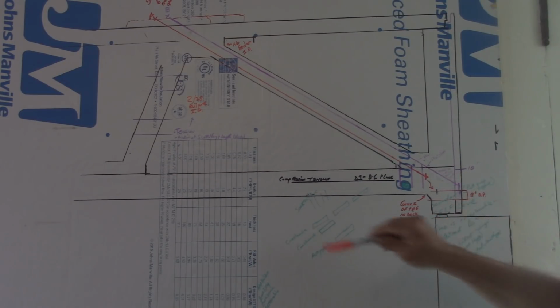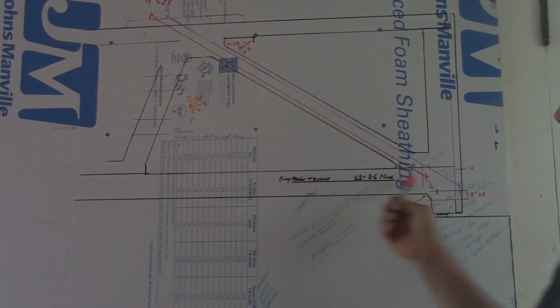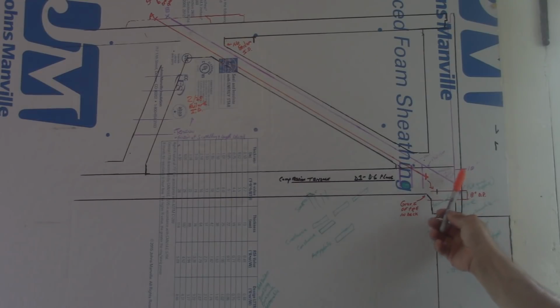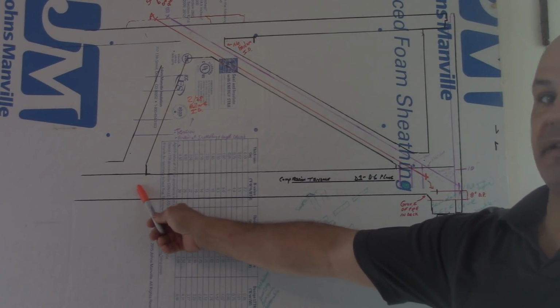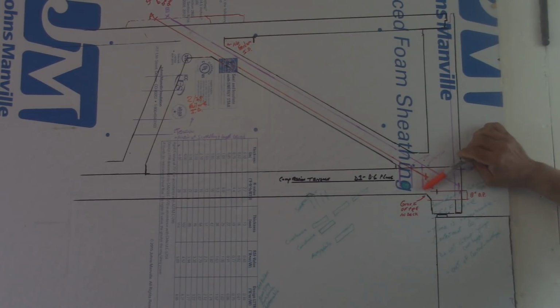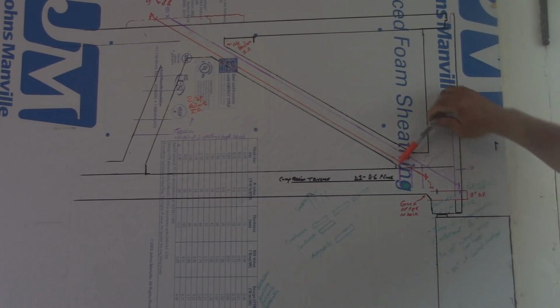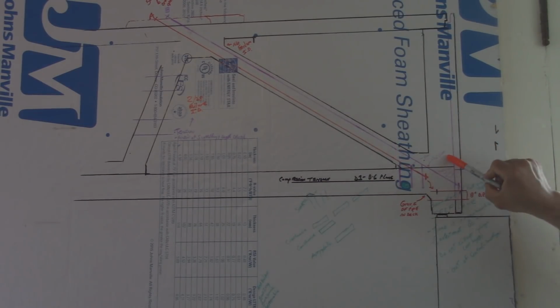system got it right. So when we see this bridge fail, this one is way out here. It's nowhere near this area here. And this has the most loads on it. This doesn't fail with that design. So I don't think that that's the issue, because it doesn't have development, and that allowed sliding of number 11 into 12, kicking it out.